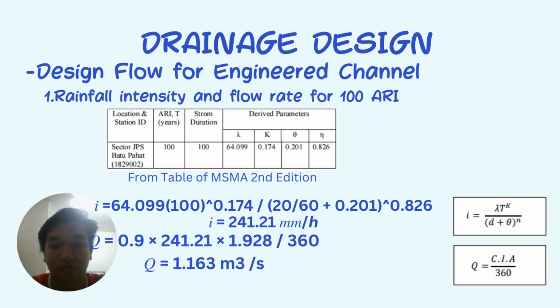To calculate the design flow for engineered channel, we need to calculate the rainfall intensity and flow rate for 100 ARI. From referring to MSMA second edition, we can derive the parameters of lambda, k, theta, and also the Manning coefficient. To calculate the intensity of rainfall, we use the formula and we will get 241.21 mm per hour. This intensity will be used to calculate the flow rate using the formula Q equals CIA over 360, and we will get 1.163 meter cube per second.